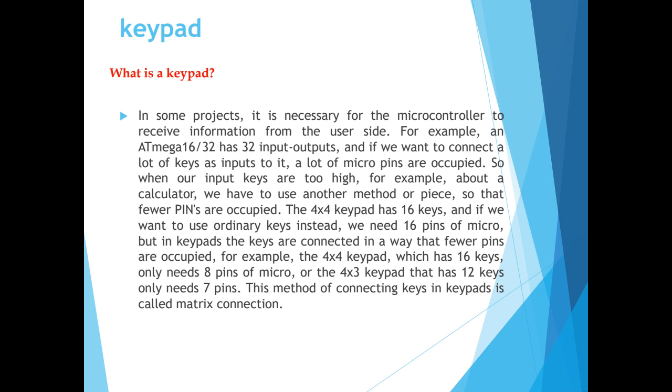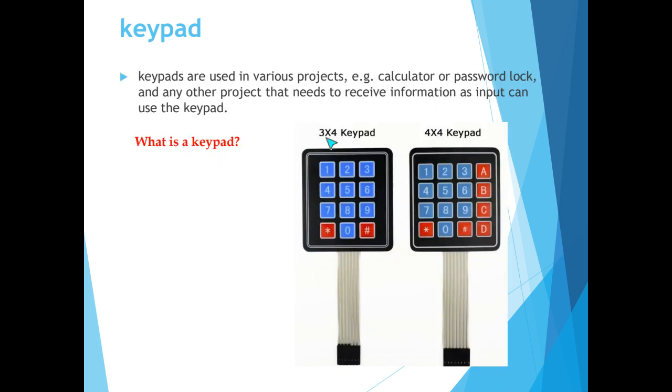But with a 4x4 keypad, when we are using a keypad form of 16 keys, we only need 8 pins of the microcontroller. Or take this type of keypad, the 4x3 keypad.